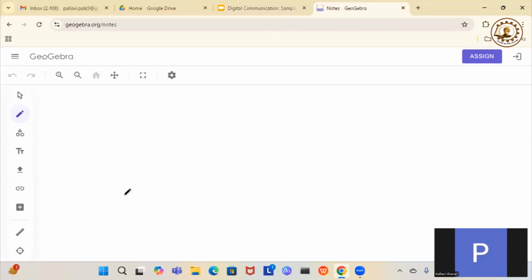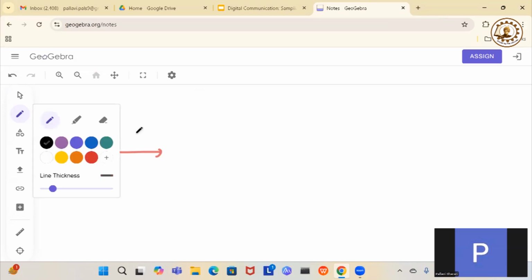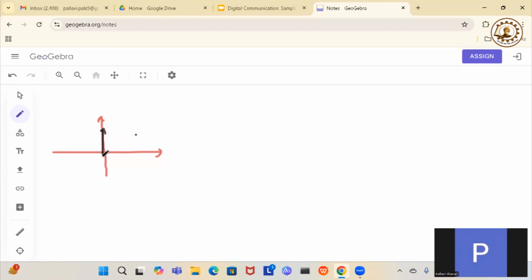So here you have this train of weighted impulses, or you can say Dirac delta functions. If I take the samples, this one is the impulse at 0, then the impulse at t, or say I'm taking the sampling period as ts, so this one is at ts, this at 2ts, then 3ts. Now here you can see there is no width. This one is minus ts, minus 2ts this way. So this is called the train of impulse function.